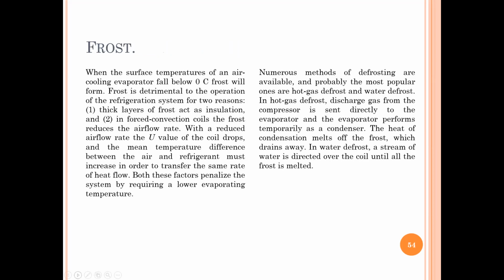Frost. When the surface temperature of an air cooling evaporator falls below 0 C, frost will form. Frost is detrimental to the operation of a refrigeration system for two reasons. One, a thick layer of frost acts as insulation. And two, in a frosted convection coil, the frost reduces the airflow. With a reduced airflow rate, the U value of the coil drops, and the mean temperature difference between the air and refrigerant must increase in order to transfer the same rate of heat flow. Both these factors penalize the system by requiring a lower evaporating temperature.